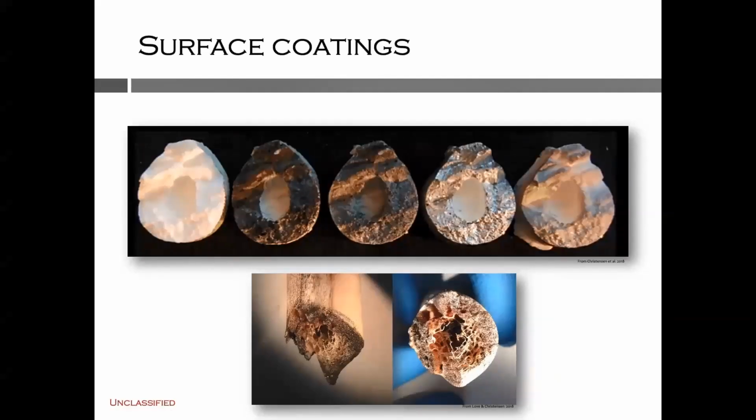Coating fracture surfaces can also help to accentuate details by decreasing the reflection and increasing the contrast. The images on the top here from left to right show bone cast replicas that have been treated in different ways. On the far left, we have an uncoated specimen, and then the next 4 specimens have been coated in order with black fingerprint powder, dual contrast fingerprint powder, silver ink, and gold sputter. The dual contrast fingerprint powder was found to best enhance the surface details. This was even better than the black fingerprint powder because the black fingerprint powder had a mattifying effect that reduced contrast.